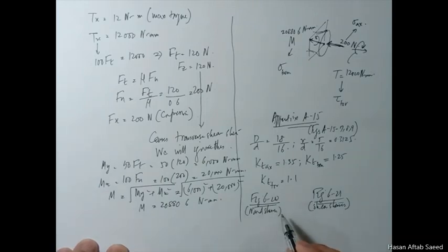Now in these figures, you have to read against the value of 5 millimeter radius and Sut equal to 900 MPa. These are the two conditions, and against these, the notch sensitivity for bending and axial is the same thing. For normal stress q is 0.92, and q for torsion will be 0.9. Again, these are very rough values, but that will do.